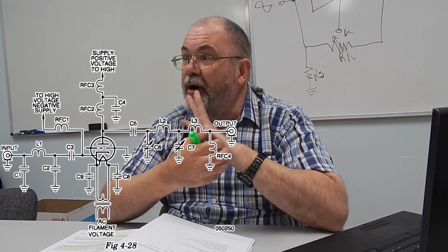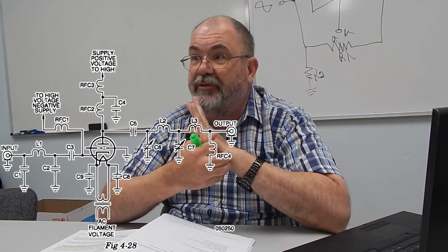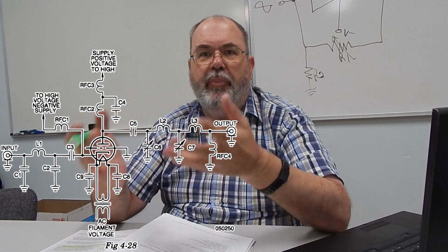Because, once again, every piece of wire in this circuit is now acting as a miniature antenna, an amplifier can turn into an oscillator in a really quick time. And what is an oscillator? An oscillator is an amplifier with positive feedback. We looked at negative feedback up there. Well, what happens if we feed back into the non-inverting input of the amplifier? The thing goes crazy. It starts oscillating. Amplifiers turn into oscillators really quick when the feedback accidentally becomes positive instead of negative.